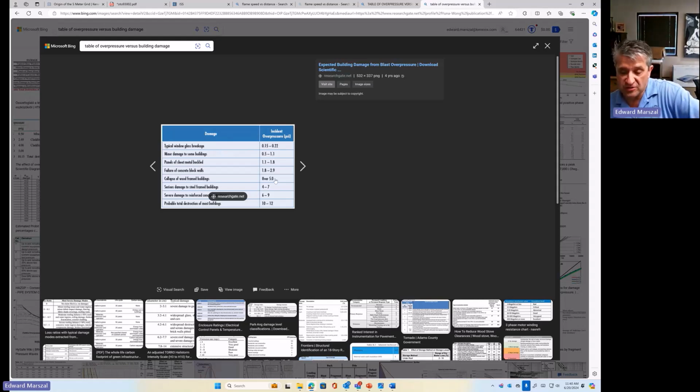Now, if you wanted to use gas detection, putting a gas detector open path over the bunded area is not a bad idea. It's not as fast as the level switch. But if you're accumulating in an area where, let's say, the spill doesn't run correctly down into your sump, you're going to be able to detect that. And if you're spilling into an area where you don't have a bunded area, you just have kind of grading and curbing, there is a place where gas detection makes a little bit more sense.